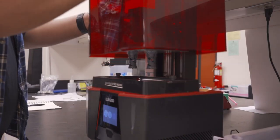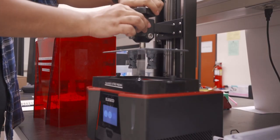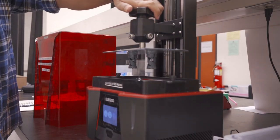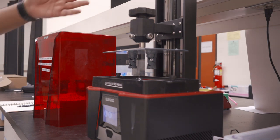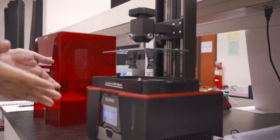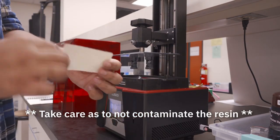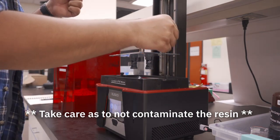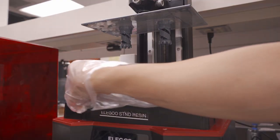When the printing is done, remove the hood. You can directly remove the part from the platform, but it is recommended to remove the platform from the printer first and then remove the part separately. Before that, try to salvage some of the resin on the plate so you can use it later. Use clean, lint-free paper to scrape off the resin back into the resin tank. Make sure to clean off any remaining residue around the tank.